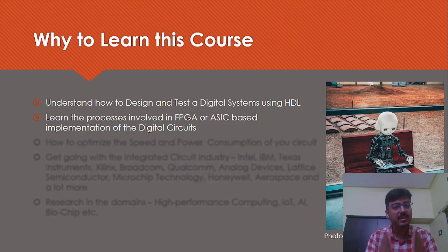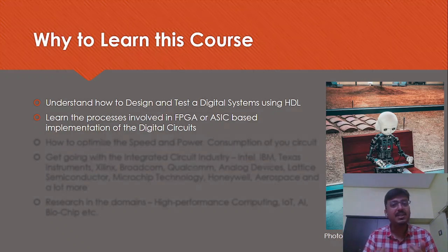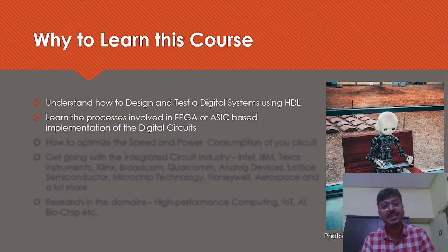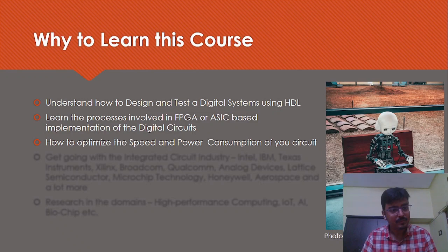In FPGA, we have a sea of configurable logic blocks and interconnects, where you can quickly dump your circuit. You reconfigure them and you dump your own circuit, and you can test it also. Whereas in ASIC, you will be designing a separate integrated circuit for your RTL. So obviously, the processes involved in these two types of synthesis are completely different. That we'll be discussing in this course. And what are the advantages and disadvantages we will also discuss.